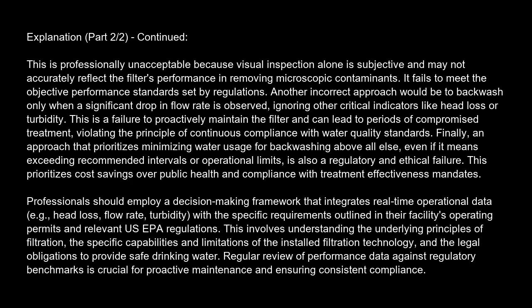Professionals should employ a decision-making framework that integrates real-time operational data, e.g., head loss, flow rate, turbidity, with the specific requirements outlined in their facilities' operating permits and relevant U.S. EPA regulations. This involves understanding the underlying principles of filtration, the specific capabilities and limitations of the installed filtration technology, and the legal obligations to provide safe drinking water. Regular review of performance data against regulatory benchmarks is crucial for proactive maintenance and ensuring consistent compliance.